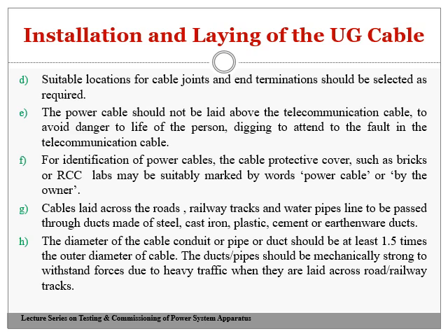The diameter of the cable conduit, pipe or duct should be at least 1.5 times the outer diameter of the cable, whether it is a cable trench or a conduit when passing the cable across the roadside.